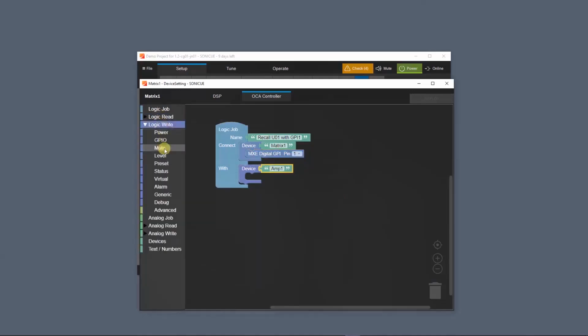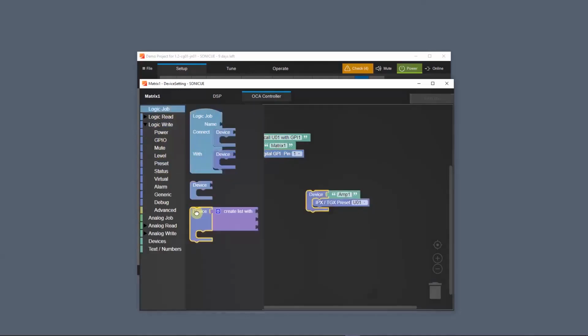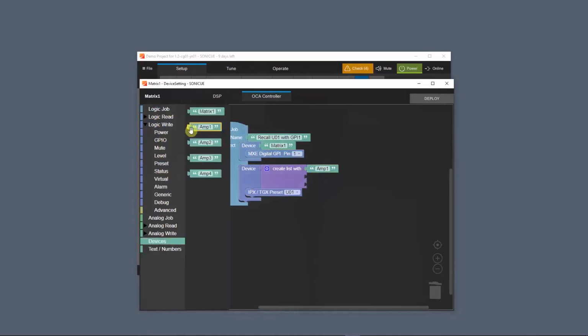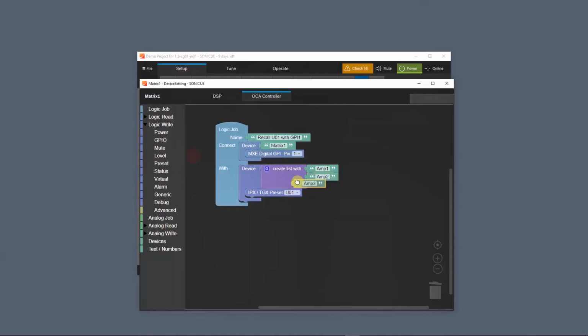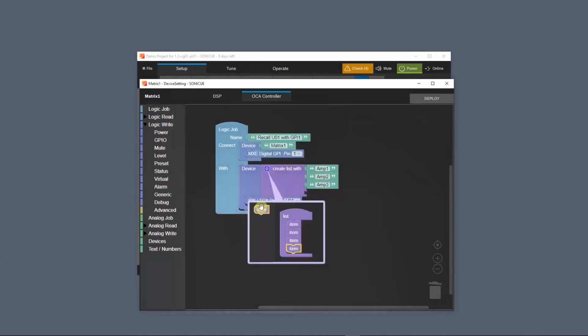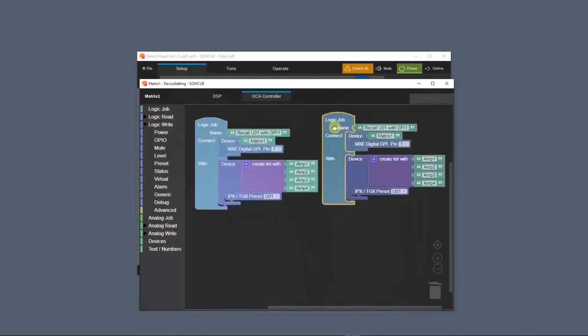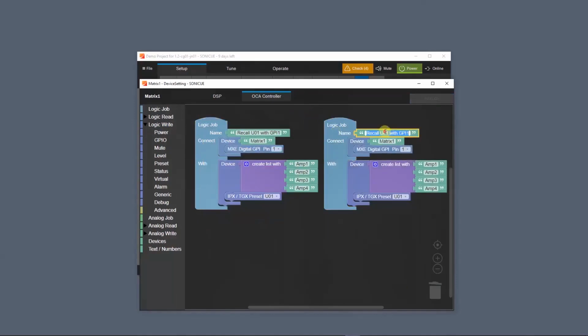And what we want to do is have this amp1. This is the label. If we had called this amplifier ballroom, then it would show up as ballroom, but we called it just amp1. And we want to change it to user preset 1. Now, this is if it's 1 amp. In our case, we have 4 amplifiers in our system, so we are adding a device that can actually handle a list. We don't need to duplicate anything. We're just saying, when this happens on top, these 3 amps, oh, we need a 4th one. So we will add a 4th one, and you can add up to 100 in this block. And this will all happen. Now, a really cool feature: we want to do a second job, which is all the same, but just using a different pin to switch to user preset 2.